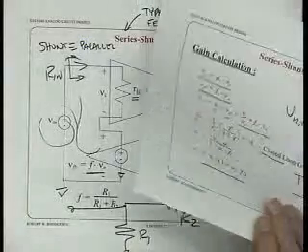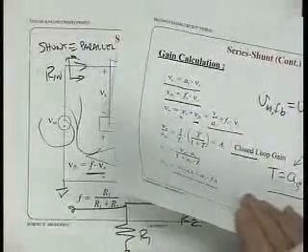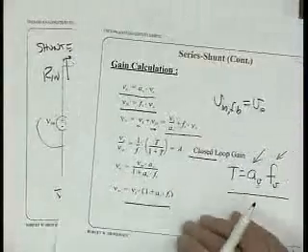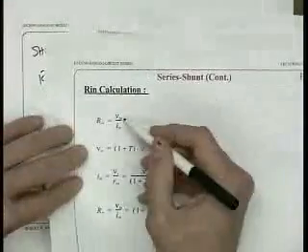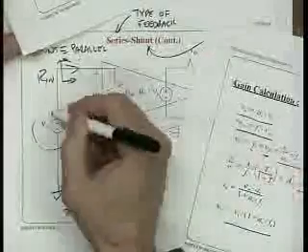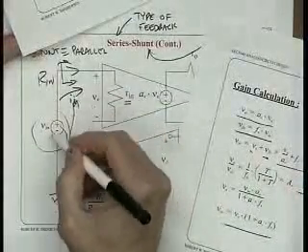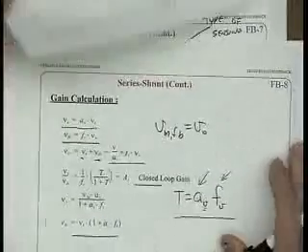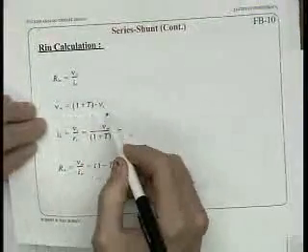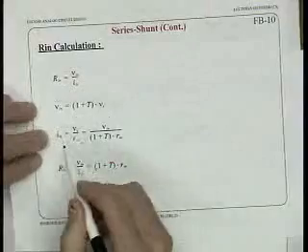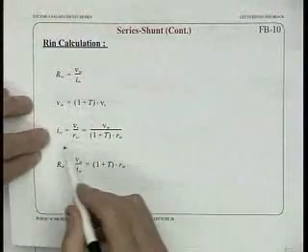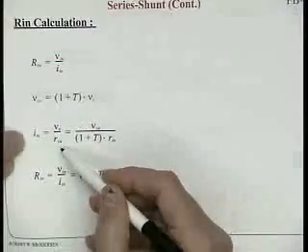All right, a little teeny bit of math. I guess I did output resistance first. It's Vin over Iin, right? So this is Vin. We need to find out what Iin is. Or this could be V test over I test. Vin equals 1 plus T times V error, as I just showed you in the previous diagram. Iin equals V error over rin.